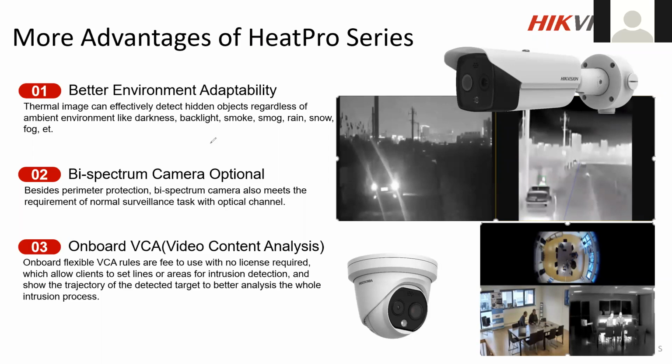So let's say there's a wall here, or maybe let's say it's a box. We have the thermal camera fixed here, looking in this direction, and here somebody is lighting up a cigarette. Just ignore my drawing skills; they are really bad, even on the computer. Now this cigarette is emitting IR radiation. Can the IR radiation go through a surface? It cannot. It reflects but never comes to the camera. So according to the working principle, this kind of scenario cannot be recognized. So definitely it has to be a surface.